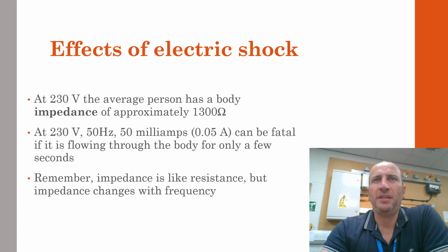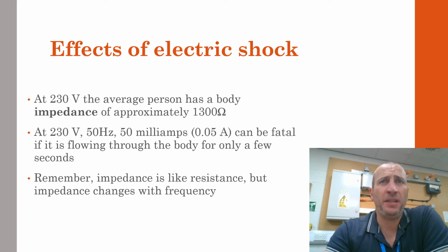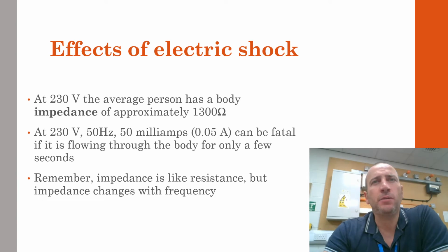You'll notice that resistance and impedance are used interchangeably at this level, but there is a difference. The only thing that has resistance only is a resistor, and this resistance will remain the same when a DC supply or any frequency of AC is applied to it. Everything else that conducts a current will have some level of inductance and capacitance, however small that may be. This means that if an object has impedance, its overall equivalent resistance will change based on the frequency of the electrical supply.